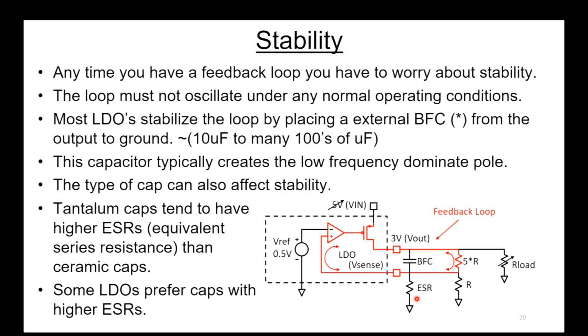Tantalum caps will probably be at the high end. You might get a couple ohms in a tantalum cap. Ceramic caps might be milliohms. Sometimes that ESR can help the LDO. Sometimes it can hurt the LDO. So different caps may add to or subtract from your stability. I just wanted to mention the difference in capacitors might make a difference if you're trying to stabilize the LDO.